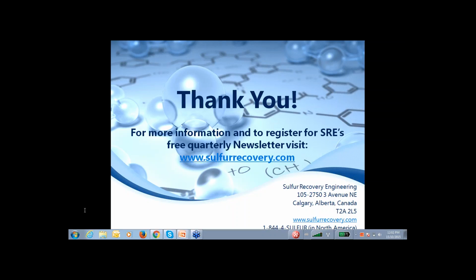Could you use both Titania and Alumina catalyst in one Claus reactor, specifically with Alumina in the top layer? This is an excellent question, and as I realize now, one important aspect that was not covered in this presentation. I did mention that Titania catalyst compared to Alumina catalyst is much more sensitive to BTEX poisoning if the BTEX components are not completely destroyed or combusted across the reaction furnace.